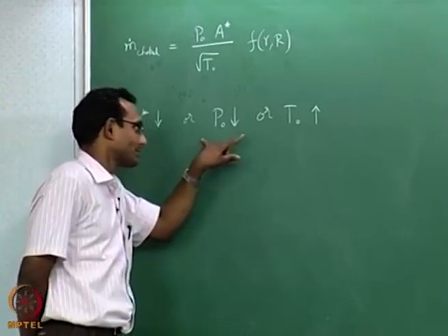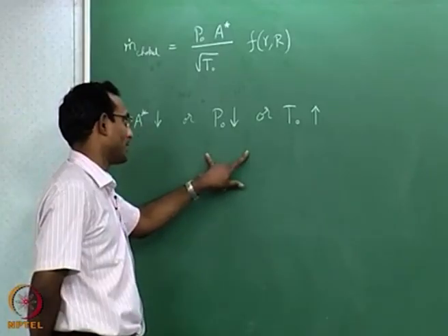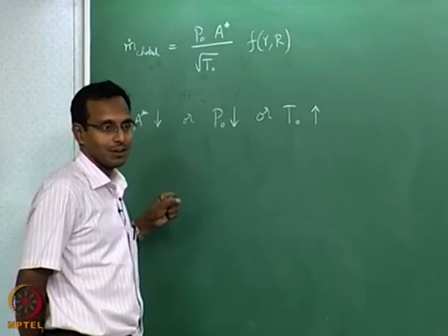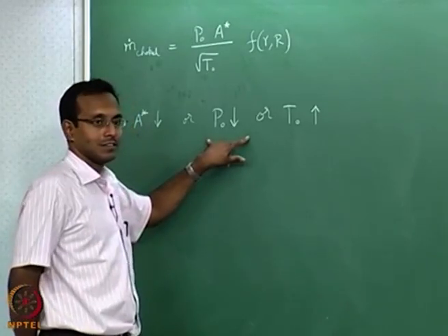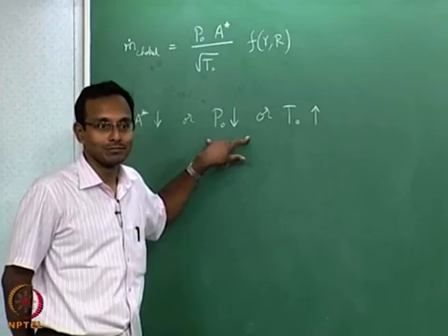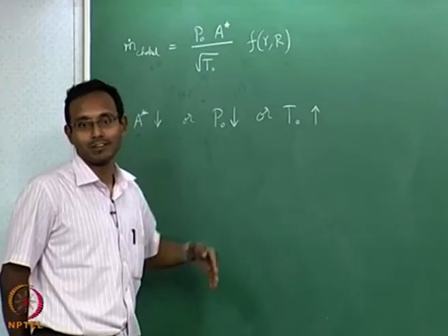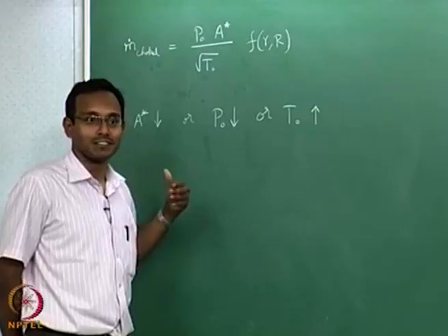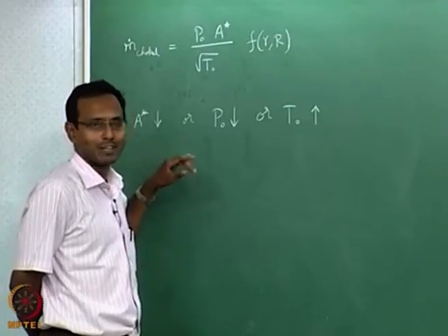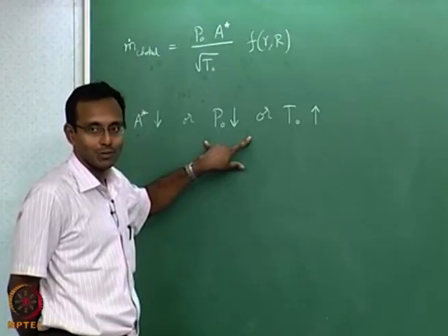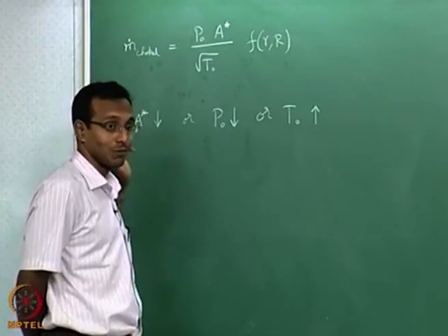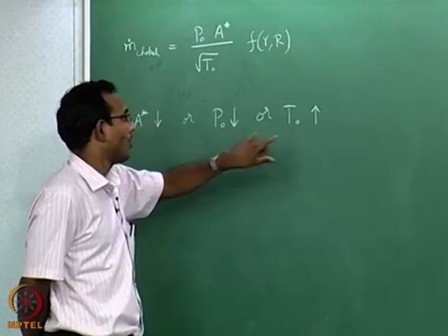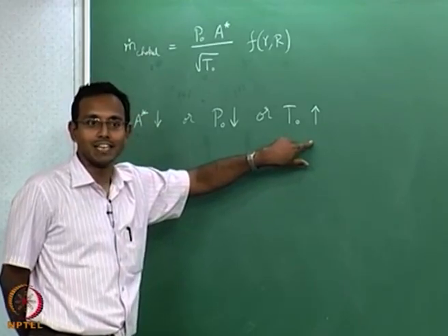Okay. So choking can be introduced in thinking about that way, or I can think about some extra mixing happening. Okay, or some other crazy geometry that there is more drag in the flow. I put some protrusions inside my duct, and that is going to cause P naught loss. Okay, or maybe there is a shock forming inside, that is going to have P naught loss. Lot of P naught loss mechanisms inside. They are all going to take the flow towards choking condition eventually. Okay, I am thinking about a flow through a duct still. Okay, and in the middle I am having some P naught loss mechanisms. Or I can heat the gas, and that will take you to choking condition.